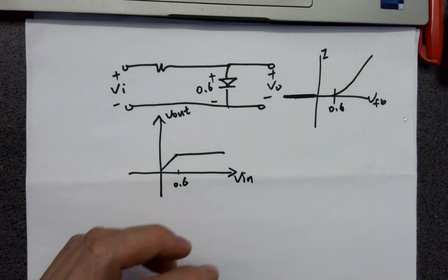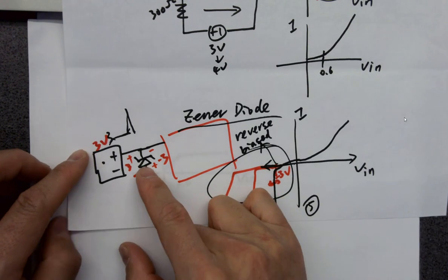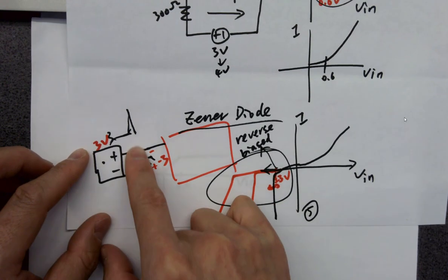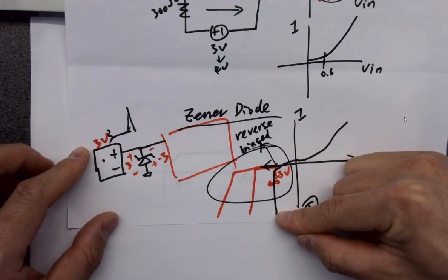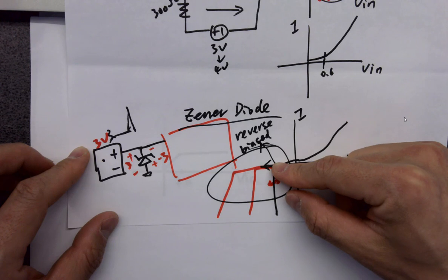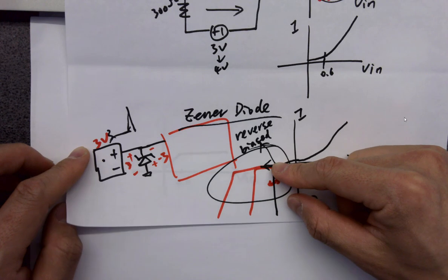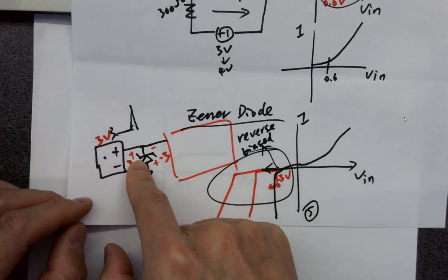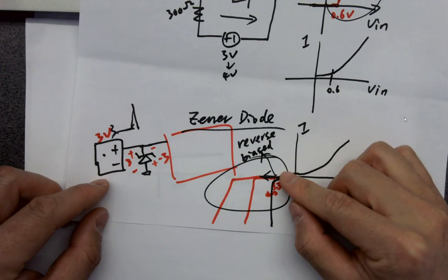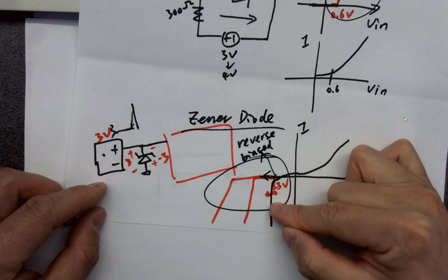If you have a Zener diode, Zener diodes are designed for reverse biasing. So at this point it breaks down, but after you reduce the voltage, it recovers. That's a Zener diode, because we use Zener diodes at the breakdown state. It reverse breaks down at this point.